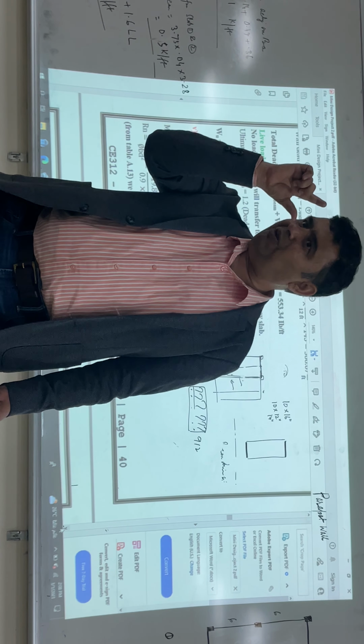That is why the code says if you are not taking the depth of the slab according to its rule, you have to check whether the slab is safe in deflection or not. If you take the code depth, there is no need to check, it is already safe. That is why generally the slab thickness is higher and the percentage of reinforcement is coming less. But the beam generally does not fail in deflection.